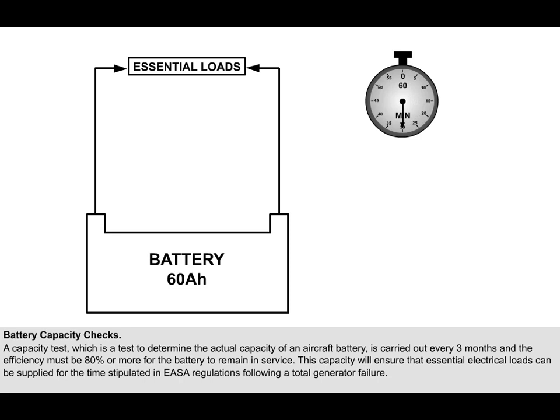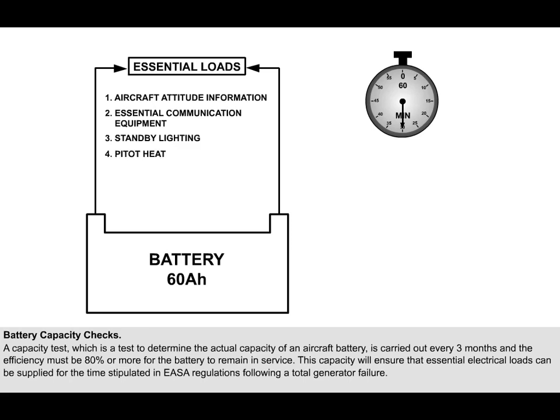Essential loads will include aircraft attitude information, essential communication equipment, standby lighting, pitot heat, plus any other services necessary for continued safe flight.